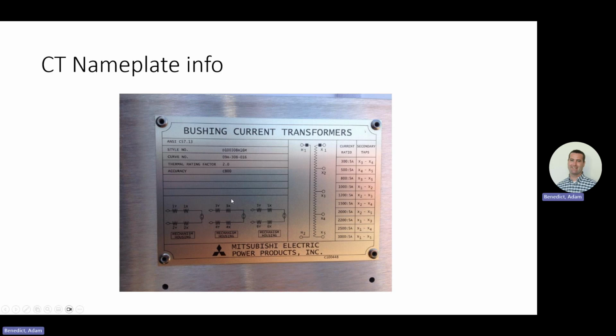So this would be your bushing 1, 3, 5, 2, 4, 6. And then you can see 1Y is closest to the bushing. Here's your breaker operating mechanism. And then 1X is on the inner. So usually you hear outer, inner, and then same thing. The Y here is always on the outer, the X is on the inner. And if there's a third, the Y would be the middle CT, the Z would be on the outer, and it's always called Z when it comes to breaker CTs. Transformer CTs are labeled a little different, but.